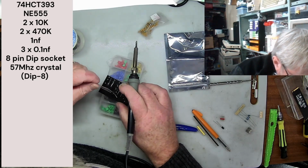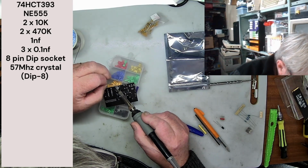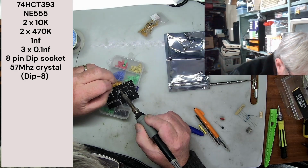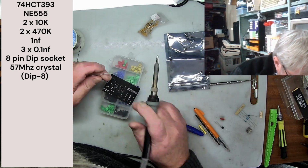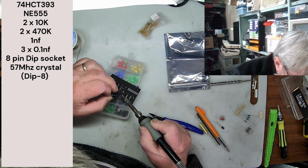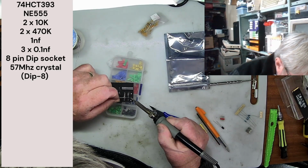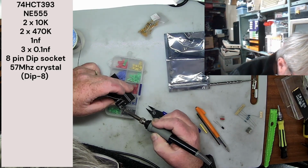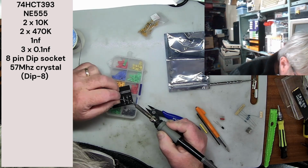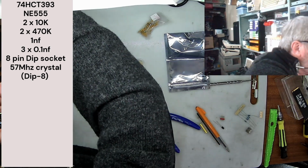So with those tacked, they're not tacked very well, so I'm going to solder the opposite sides. That just means that if I try to solder one side, it doesn't come undone and move on me. Yep, that one's done.